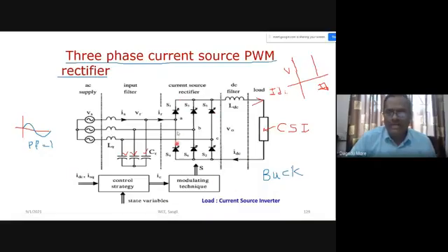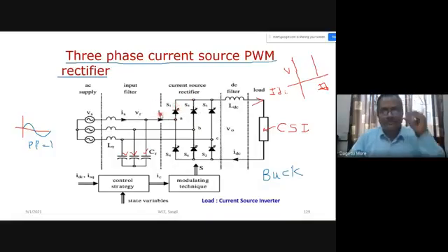But what type of devices can we use here? What is the symbol? Can you identify the name of the device used here? GTO. Here it is a GTO. The symbol is a thyristor symbol with the gate crossed, which means it is the symbol of a GTO. The device used is the GTO, and we can use it in high power applications. Again, the power flow here is bidirectional. Are you getting what I want to say? The power flow in this case is also bidirectional.